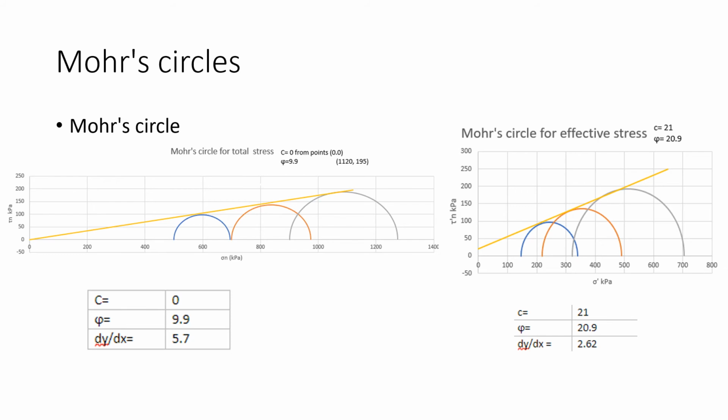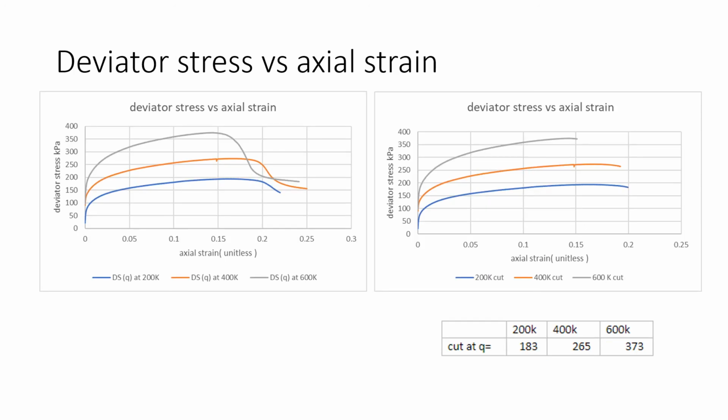This cohesion value is high enough that we would expect to have a sticky clay, therefore on the slope we could withstand a high loading value. On the left, we observe the uncut graph for deviated stress and axial strain. The loading behaviors are as expected until failure.